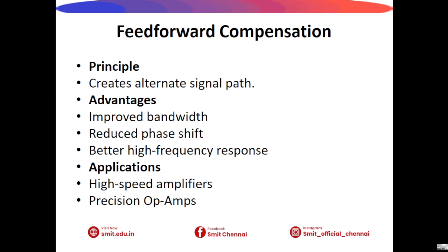Next, we see about the feed-forward compensation. Feed-forward compensation creates an alternate signal path that bypasses certain amplifier stages. This reduces phase lag and improves high-frequency response. The technique is commonly used in high-speed amplifiers where maintaining bandwidth and stability simultaneously is important.